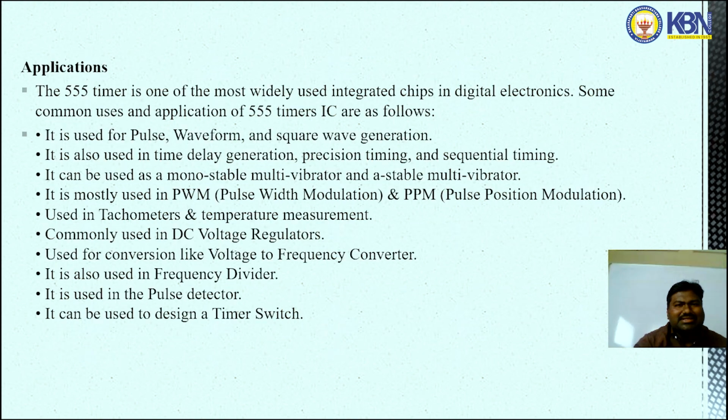This is about the IC 555. The last topic of IC 555 is its applications. It is used for pulse, waveform and square wave generation. It is used for time delay generation, precision timing and sequential timing. It can be used as a monostable multivibrator or an astable multivibrator.